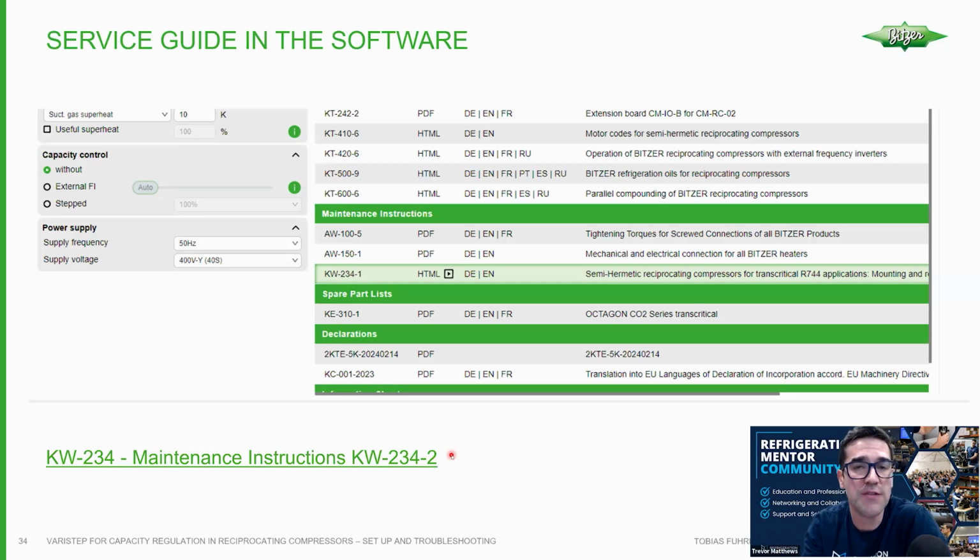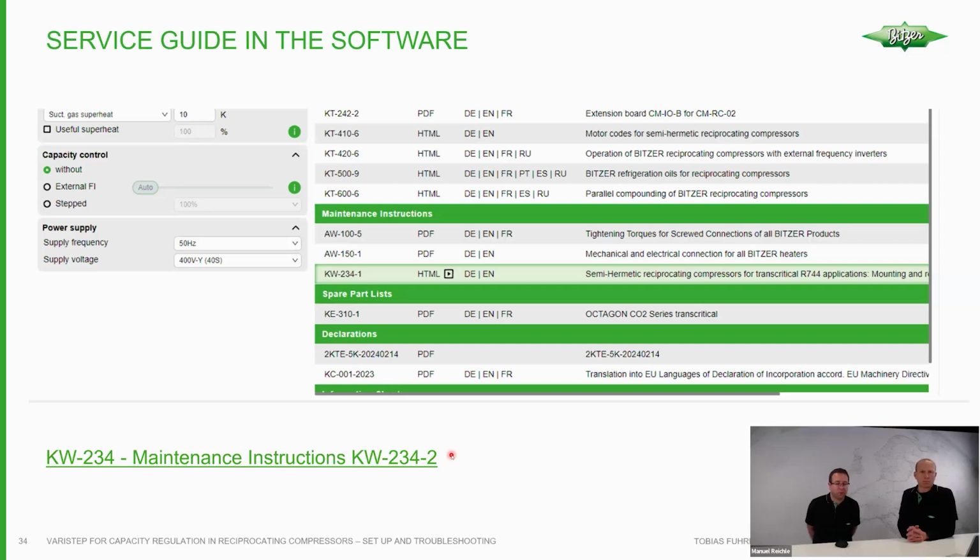Do you want to talk about 4 or 5 things that they can go and check to verify that the compressor is running properly? So I would bring the system into stable conditions. A little bit higher suction pressure is maybe better than too low. So if I run the system at stable conditions, I would take off the solenoid coils from the compressor. Of course, we discussed this earlier before the call. We should take care that we don't overheat the coils, so we should put a screwdriver in or disconnect the coils from the plug.